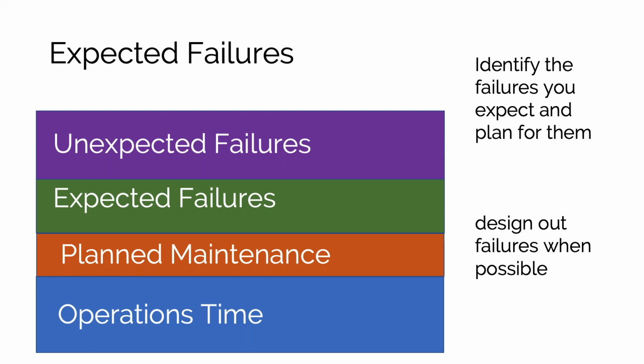We know that will happen. And if it's a small diameter pipe that's really just serving a few customers, I don't have to do anything to prevent that failure. I could choose to, but I don't necessarily have to, because it's not a really high risk event. The consequences aren't that great. So I can just react to that failure when it occurs and fix the pipe. So that type of failure is an expected failure.